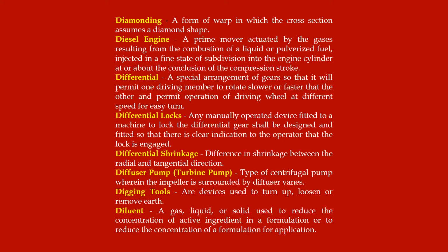Diesel engine. A prime mover actuated by the gases resulting from the combustion of a liquid or pulverized fuel, injected in a fine state of subdivision into the engine cylinder at or about the conclusion of the compression stroke. Differential. A special arrangement of gears so that it will permit one driving member to rotate slower or faster than the other and permit operation of driving wheel at different speed for easy turn.